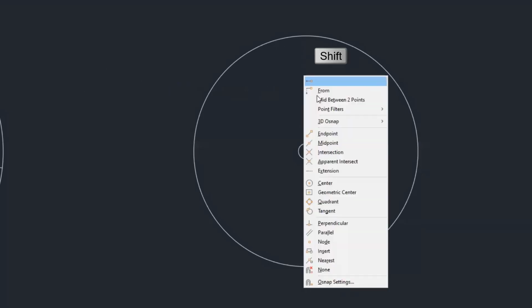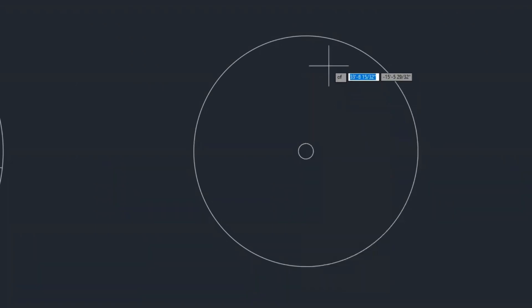And that's the center. Next thing to do is draw the line. Only this time I'm going to start from the top and I'm going to take it down. I'll go back to my line command. I'd like to pick the quadrant point. So shift right click, quadrant. I pick this quadrant point here and I bring it down and I'll draw it for now a length of 12 inches. And then I'll enter to terminate the command.